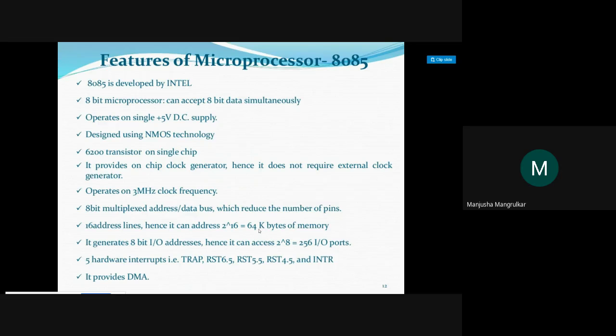Suppose you have designed your system just to monitor smoke, so your process is going on just monitoring, but a large amount of smoke comes, so you need to sound the alarm. So your currently executing program is interrupted, and it runs the buzzer program. That is called hardware interrupts, right?